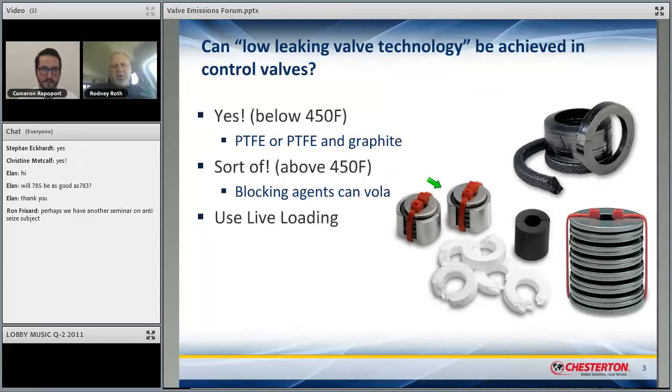The stack you see on the right, which does not have the OD guide on it, those are going to be done by torque or by measurement. That's very common and very standard as well. And there are cases where you can't get the OD guide in there, but there is an ID guide inside of that other set as well. But it's much easier for someone who doesn't have a torque wrench to properly load the ones with the OD guide.